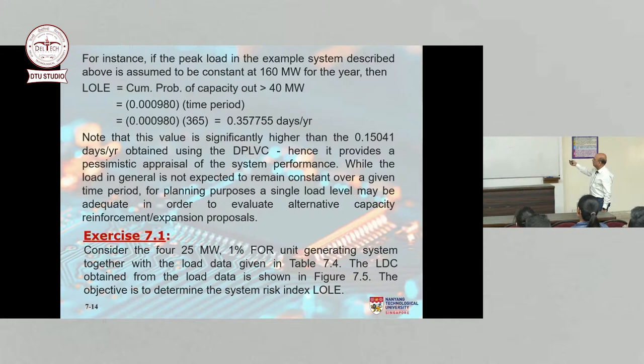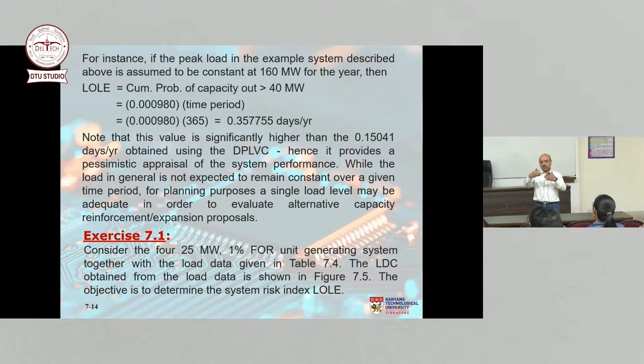So while the load is not expected to remain constant, for planning purposes, a single load level may be adequate, especially when you are comparing alternative strategies, alternative options. That's all I'm saying. So you have the option. You want to consider the load curve, which is so uncertain in the future, you can do it. Alternatively, just use a constant load level. You get an idea of what kind of risk will exist in the system.